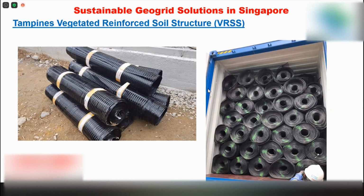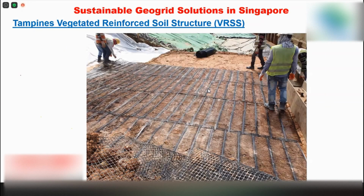You can actually get just one worker, or two workers, to handle a single roll of Geogrid without any problem. And in terms of transportation, you also save a lot of CO2 footprint because it can be compacted very effectively. Now, after the rolls are laid out, this is how it's seen on site after it's been rolled out. This is the view that you will see before it's actually compacted with the soil on top.